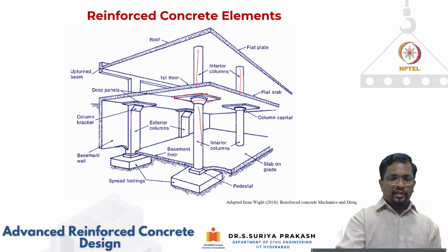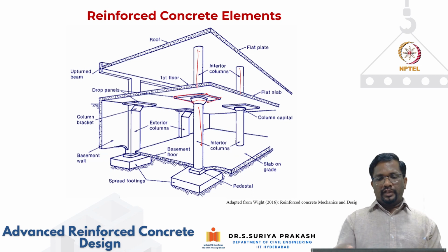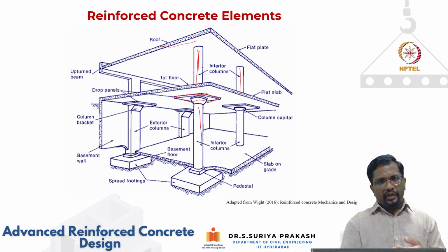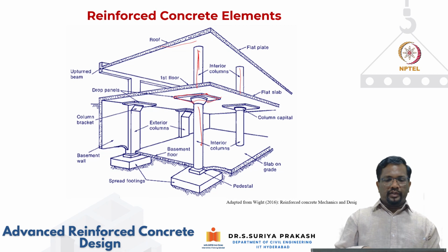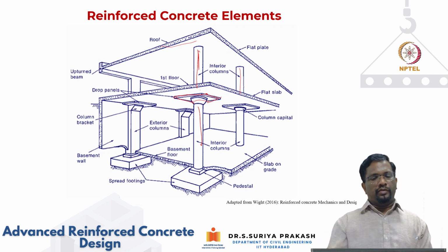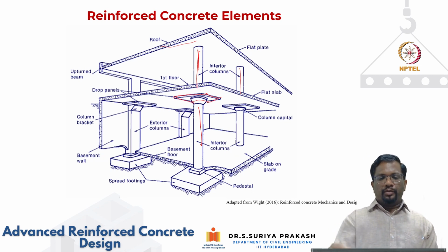In fact, in flat plate, this is one of the things that we need to be very careful about as a design engineer, because the slab loads are directly transferred to the column over a short area. If you're not very careful, then you can have a punching shear failure. So in the later modules, we will talk about how to design these slabs for two-way shear and one-way shear and so on. But you have to be careful.